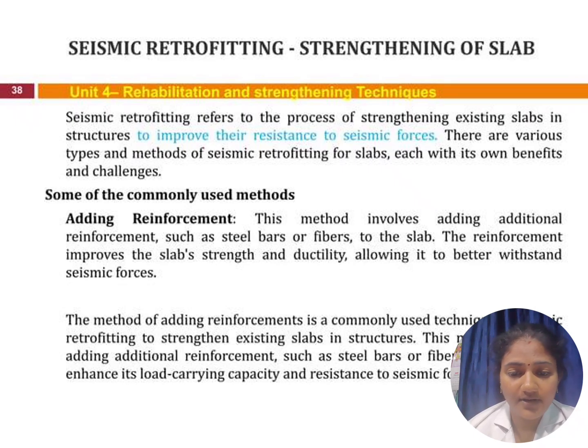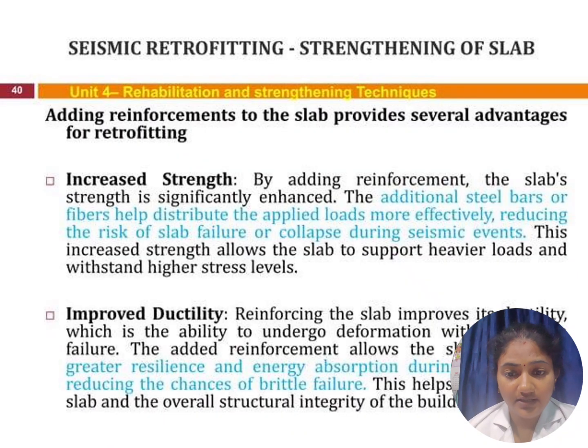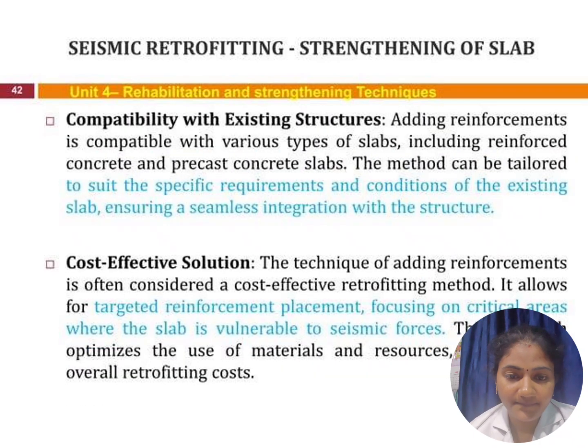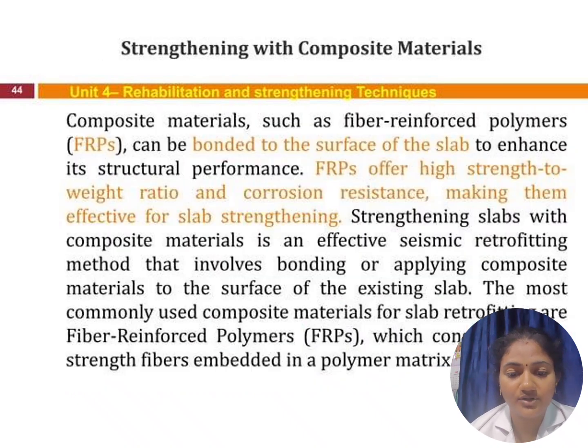And some common additional methods are adding reinforcement to the slab and providing some extra strength to the slab. And it has some advantages. It provides increased strength, improved ductility, enhanced crack control, and better load distribution. And it is a cost effective solution with preservation of the existing slab. We minimize the disruption to building occupants and reduce the need for extensive demolition, and it results in a quicker and more efficient retrofitting process.